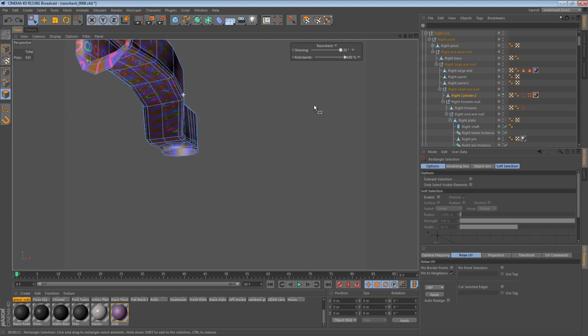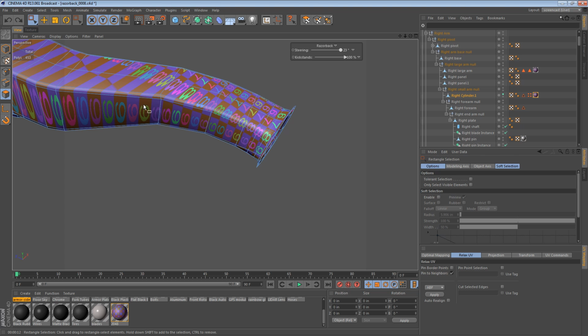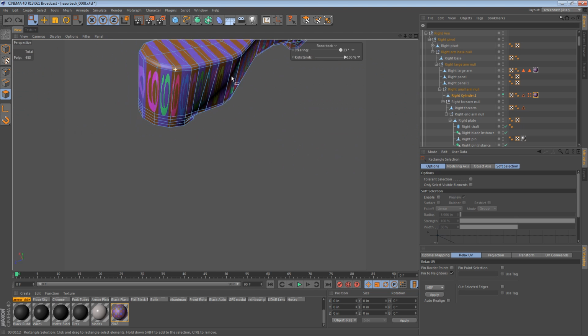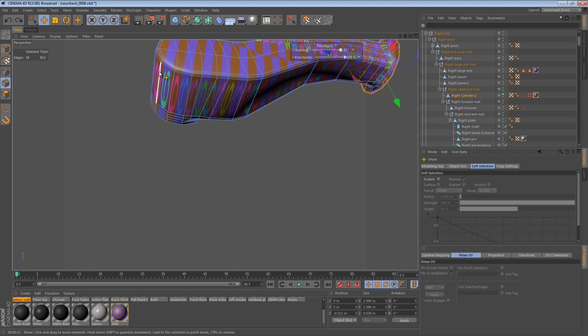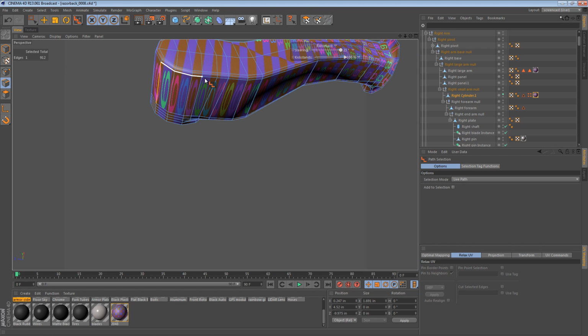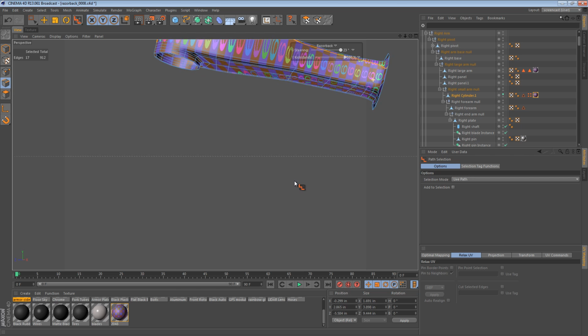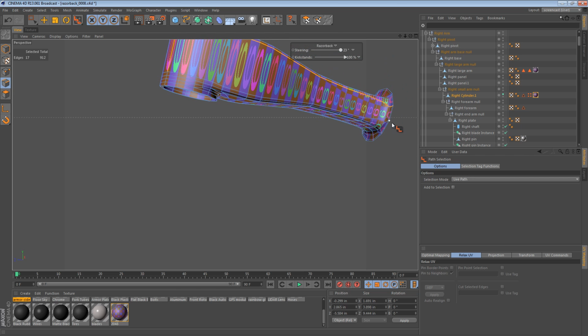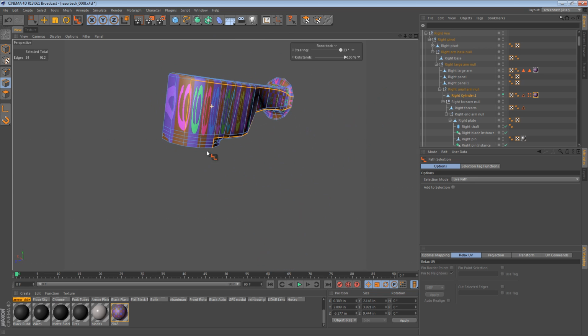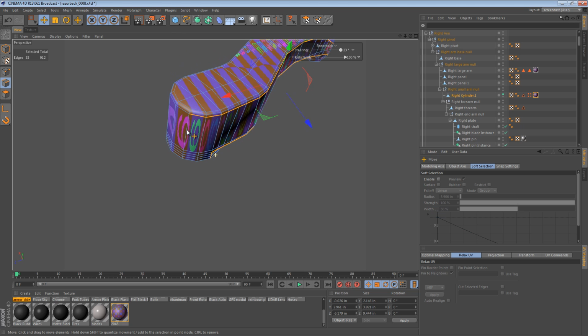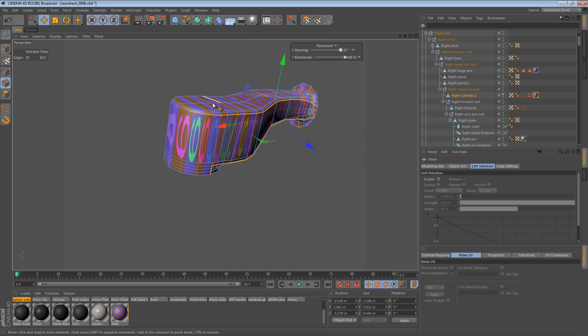Now, I'd mentioned earlier that I'm fine if there's a seam running along right here. And just for discussion's sake, let's try to unwrap it using a pattern kind of like this. So what I'm doing here is I'm drawing my cut lines. So I'm going to cut the geometry along this line as we do our mapping. So this may not be enough, but let's try it.